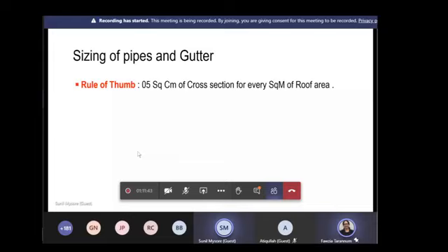So far as the cross section is concerned, height has some kind of bearing, but generally the higher, the more head, so the pressure will be more. Instead of a 4 gauge pipe, you may have to go in for a higher gauge of pipe, maybe 6 or 8 gauge, because as the height increases, the head of water also increases. There is a relationship between height of discharge and surface area. If you refer to the National Building Code, you will get more detail.